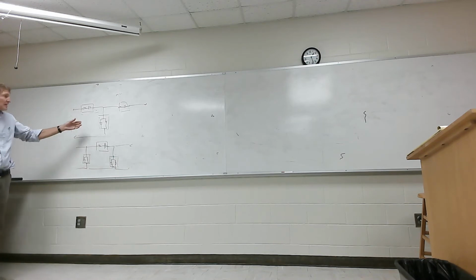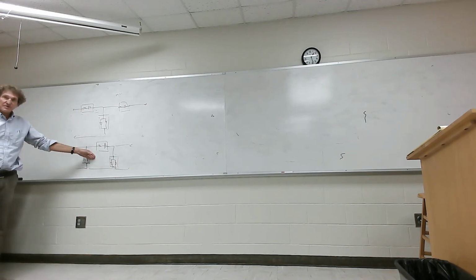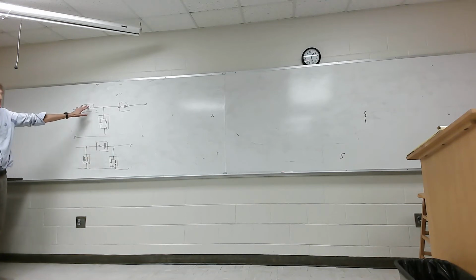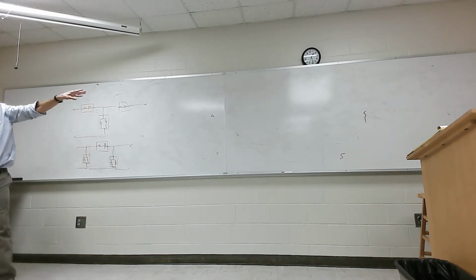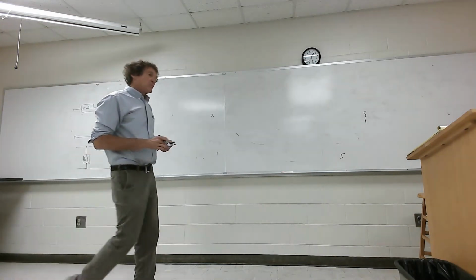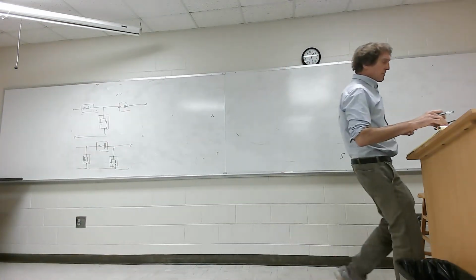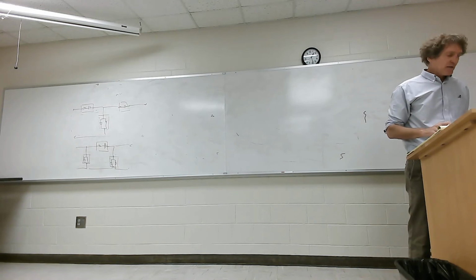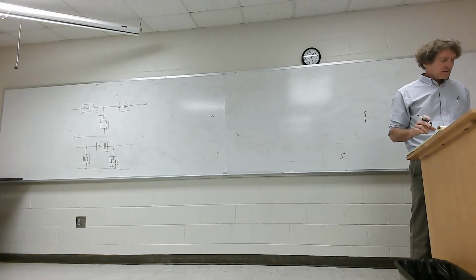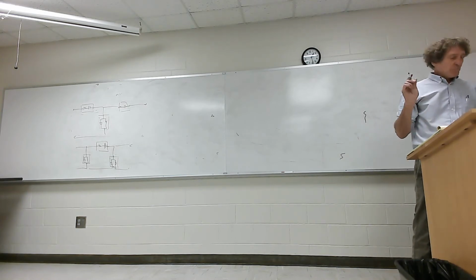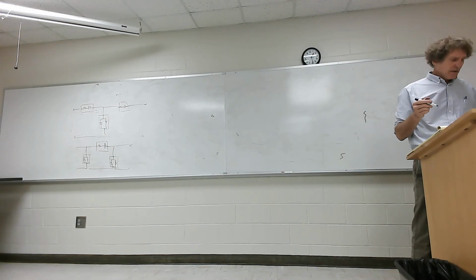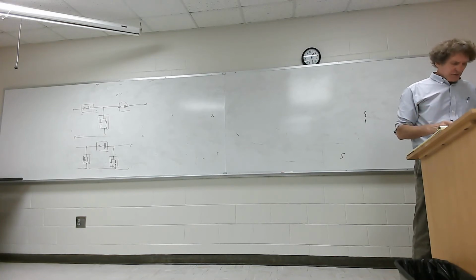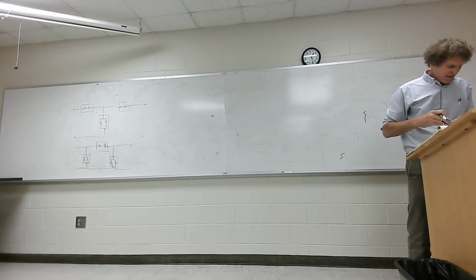So you could have either a T or a pi filter in this configuration. The values you're going to get are going to be based on a low-pass filter first design. That's the way Whitworth did it. Doesn't have to be this way, but I think in retrospect, he's probably right about this. So if you have your books and you look at page 590, what he does is he starts with a low-pass filter design. We're going to do this one.